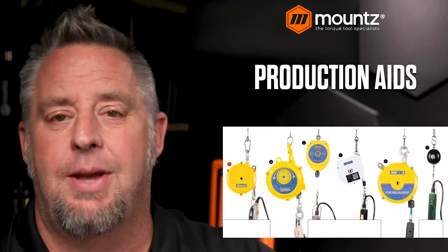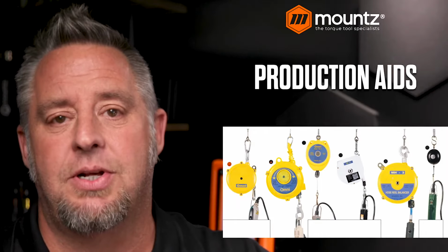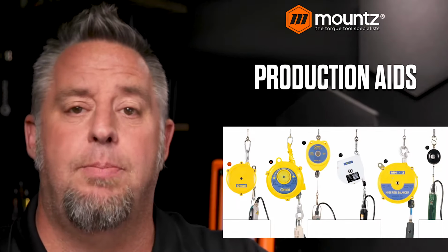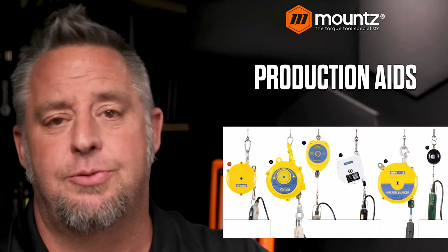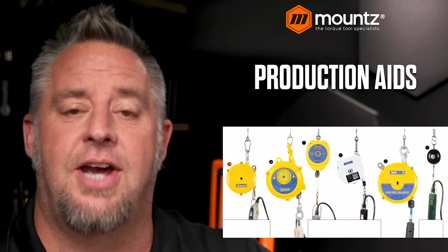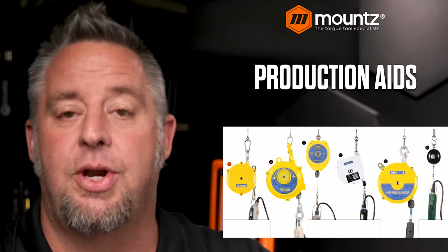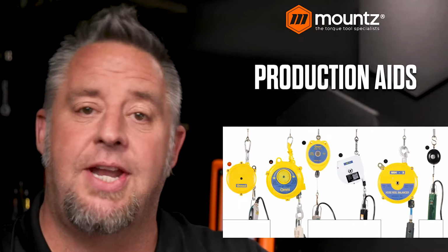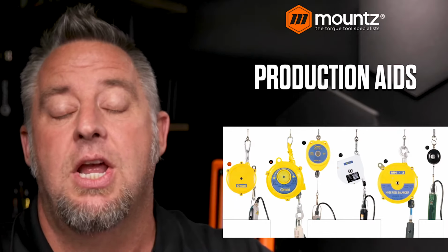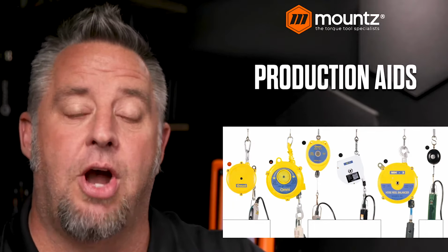There are basically two types of balancers that we typically see with the tool being suspended above the work surface: a spring tension type of balancer, and a zero gravity type of balancer. The spring tension allows the operator to pull the tool down, use it, and then the tool will want to retract back up out of the way for the operator to continue their operation.